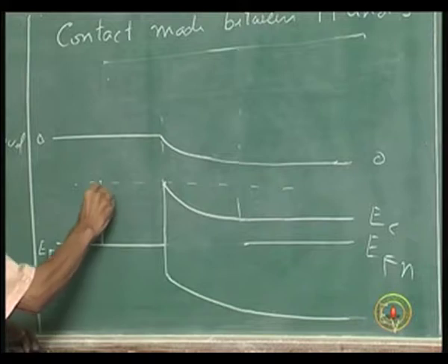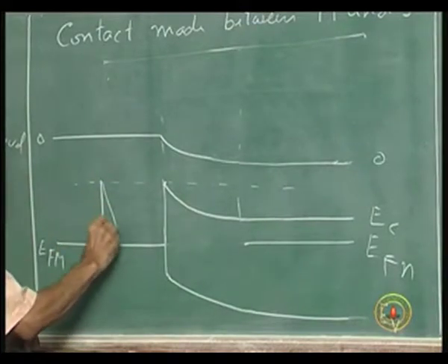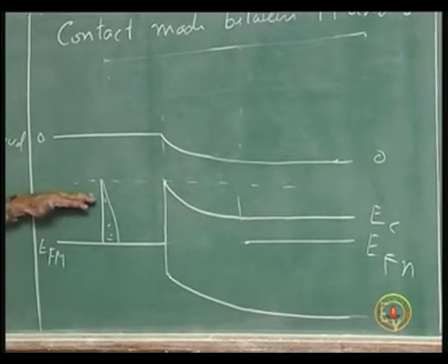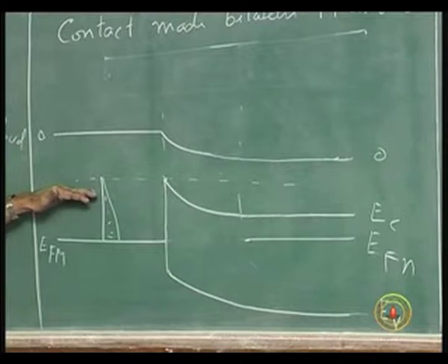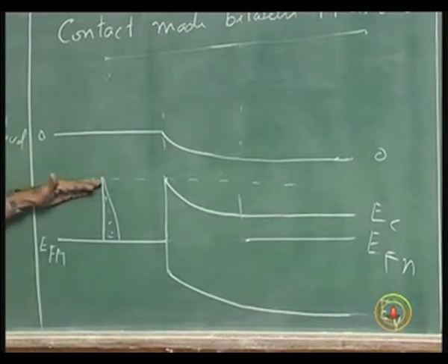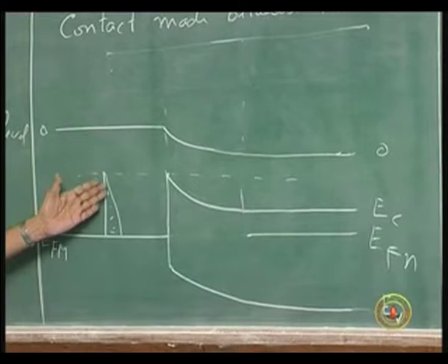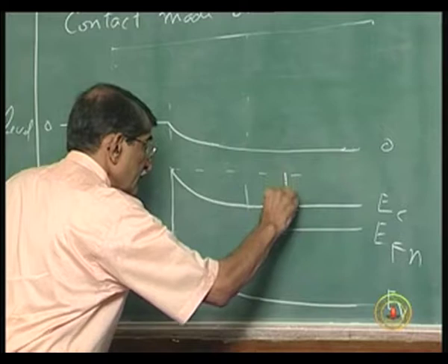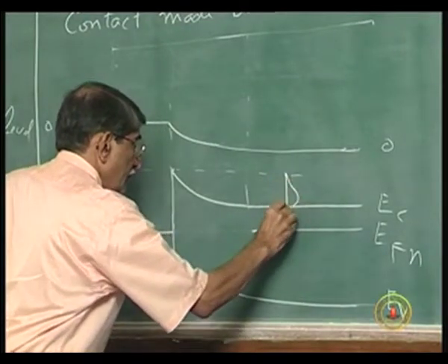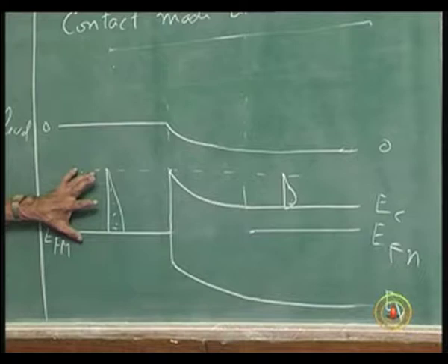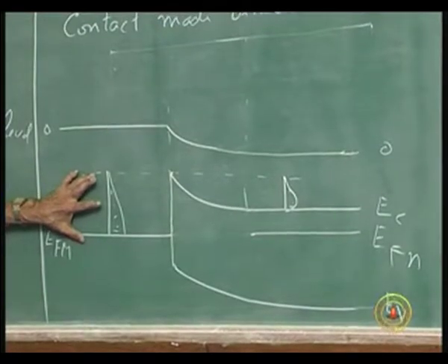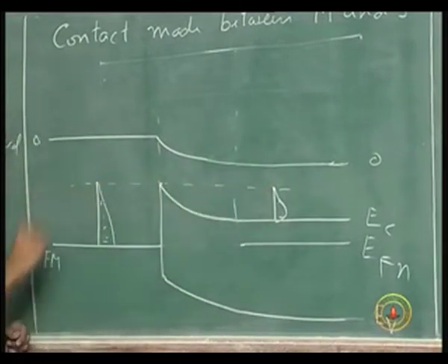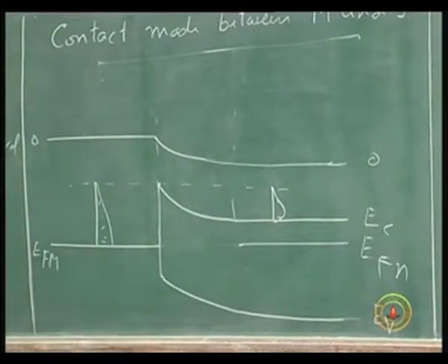Whatever energy distribution is present here, that is the energy distribution. Fermi-Dirac statistics, levels are present all through in this metal in large numbers. So, I just draw the Fermi-Dirac function itself that will give that. It does not go to 0 there, and here this will be the distribution. All that has happened is, these levels have equalized such that the tip of this and this matches. That is what is shown here.